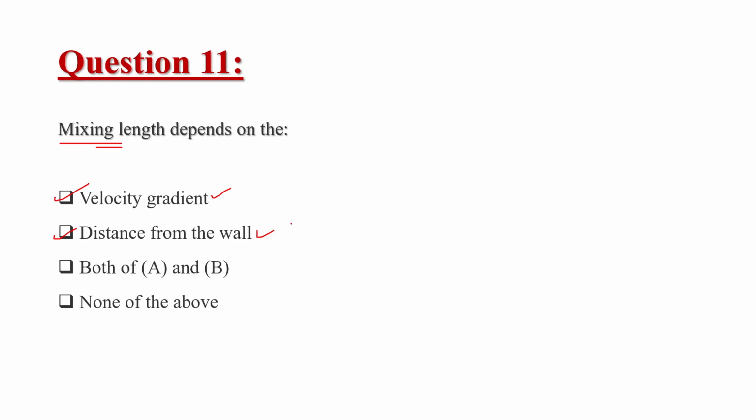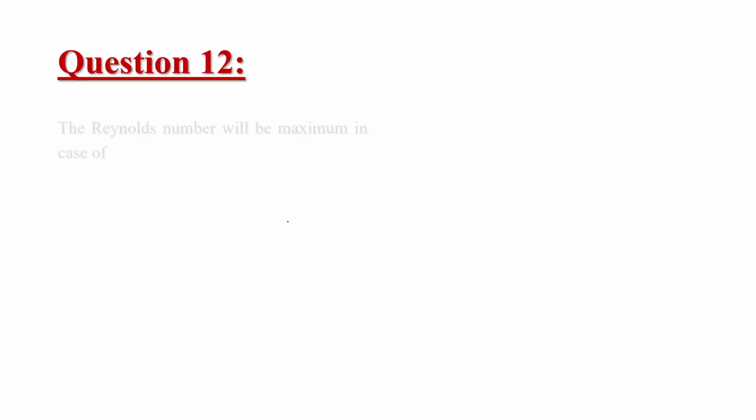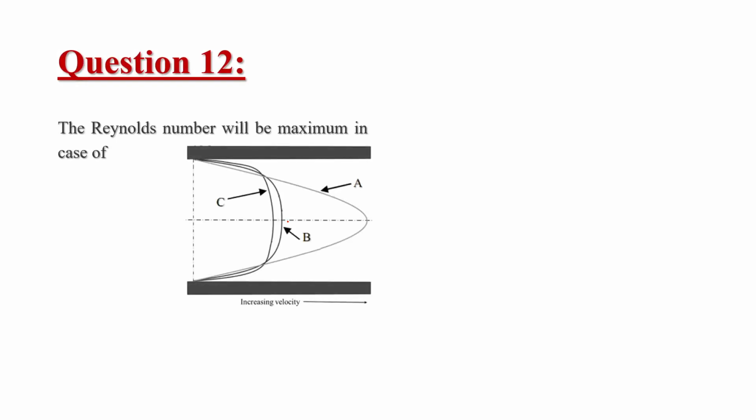Okay, which is also equal to 0.66 or 0.67 times u max. So u mean is equal to 0.67 times u max. So this is the relation. I hope this is clear, right? So how we are getting this relation of u mean, the average velocity, and how it is related to the maximum velocity. Okay.